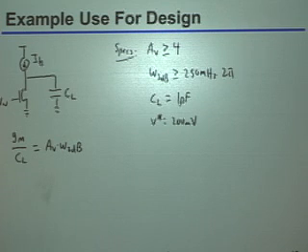Okay, good. So I don't think I need to rederive it, but if anybody would like me to, just let me know. This of course comes about because the gain is just GM times R, and the bandwidth is just 1 over R times C. So if you take the product of those two, you just get GM over C. Okay, so what was the relationship between GM and V star and the bias current, just by definition? You can flip back one or two slides if you need to. There we go. GM is just equal to 2IB over V star.